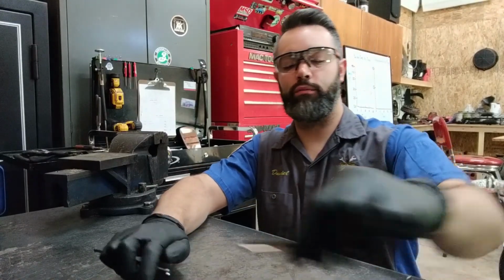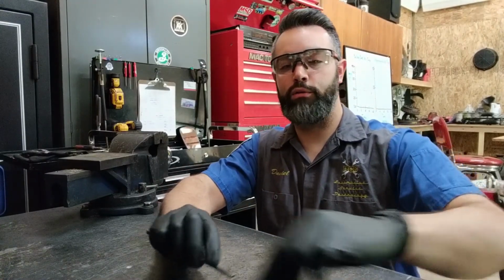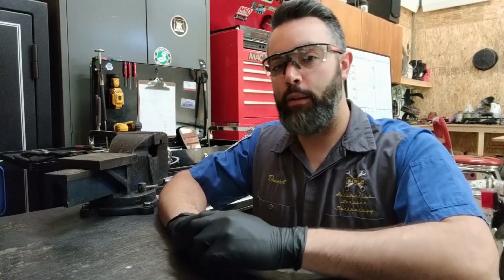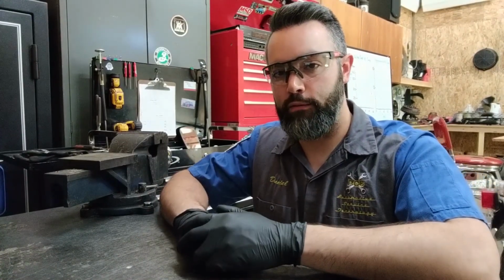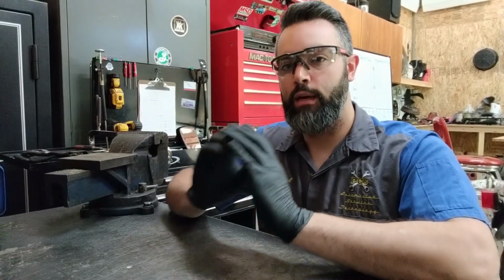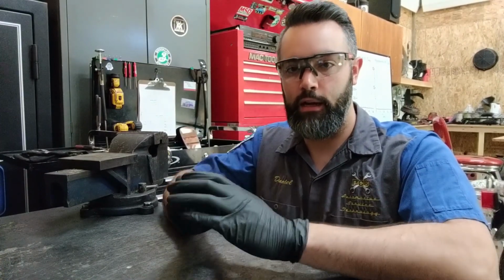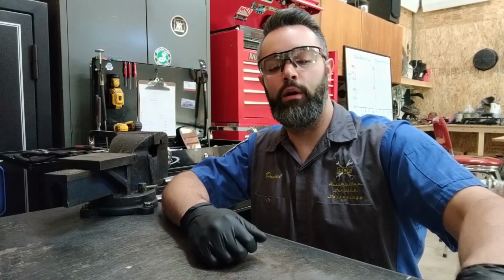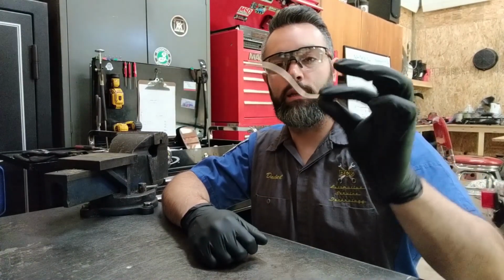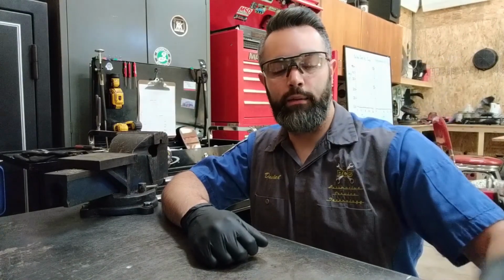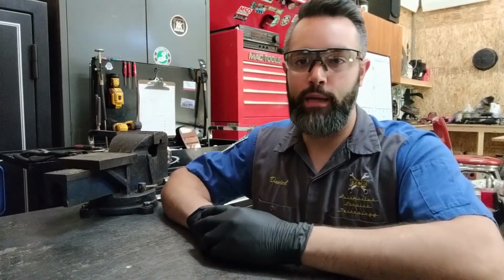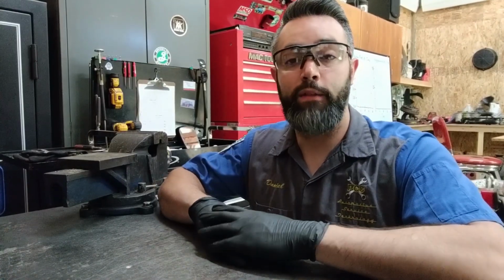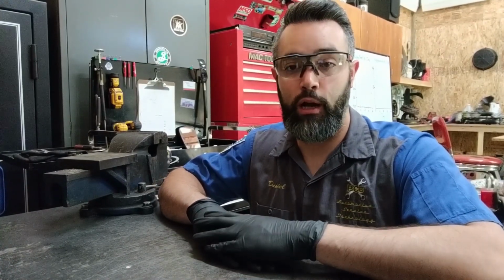So the copper is there to reduce corrosion, be resistive to corrosion and other problems. And as that moisture content increases inside the fluid, it's going to strip away that copper lining on the inside of the brake line, whether it's steel line or the nickel copper, often referred to as NICOP brake line. The inside lining gets stripped away and that starts to mix itself into the fluid. There are a couple methods that we use to test the moisture content of fluid.